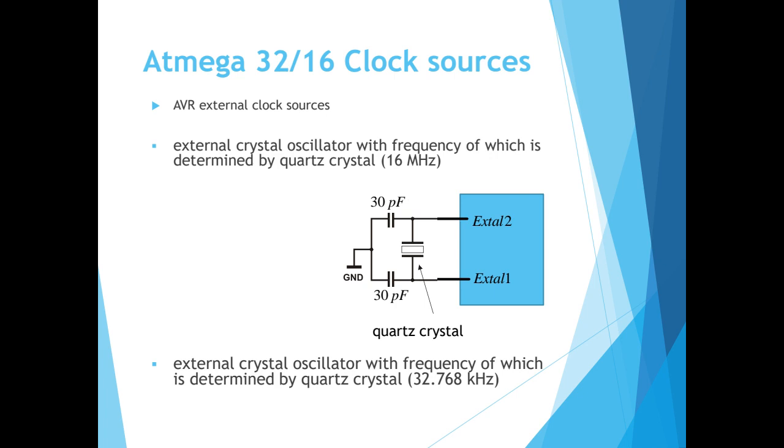And then from both sides, XTAL1 and XTAL2, they are connected to capacitors with the value of 30 picofarad, and then both of the capacitors are grounded.